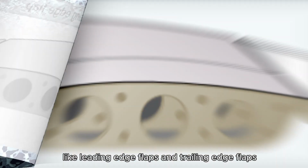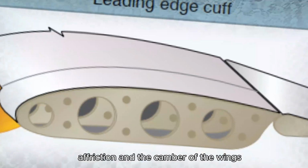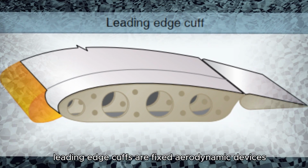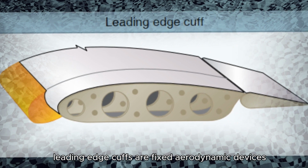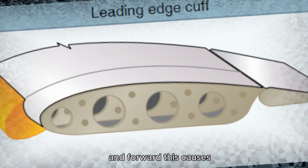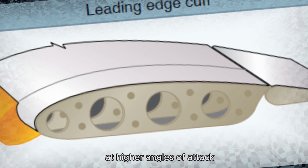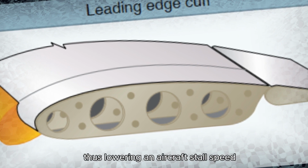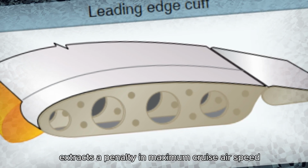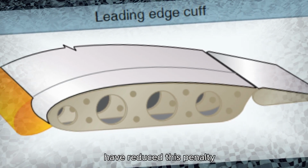Leading edge cuffs, like leading edge flaps and trailing edge flaps, are used to increase both coefficient of lift and the camber of the wings. Unlike leading edge flaps and trailing edge flaps, leading edge cuffs are fixed aerodynamic devices. In most cases, leading edge cuffs extend the leading edge down and forward. This causes the airflow to attach better to the upper surface of the wing at higher angles of attack, thus lowering an aircraft's stall speed. The fixed nature of leading edge cuffs extracts a penalty in maximum cruise airspeed, but recent advances in design and technology have reduced this penalty.